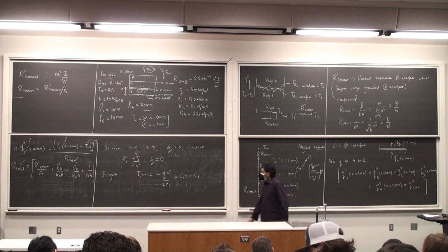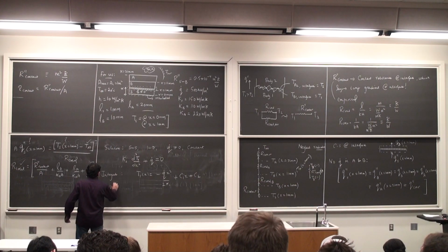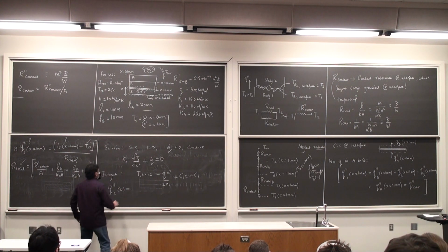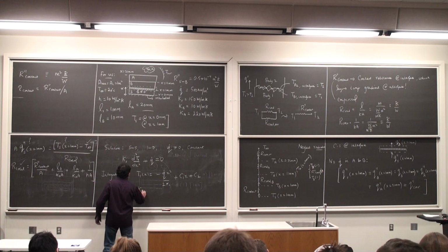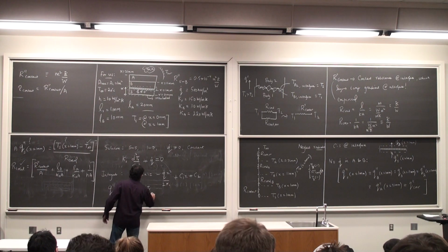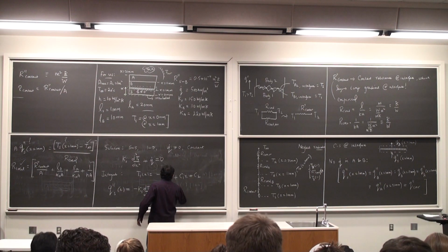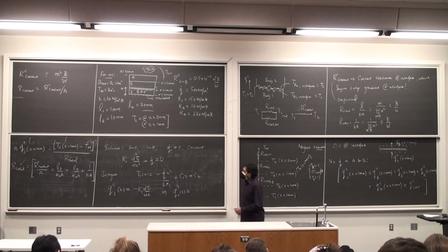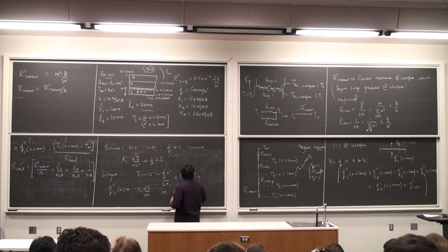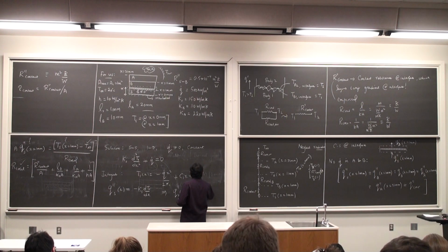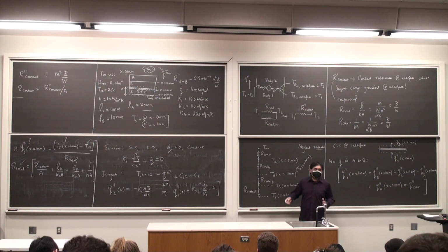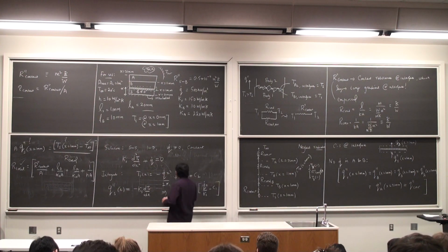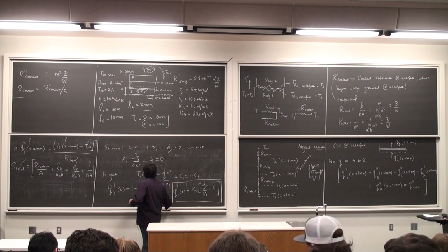I have two equations essentially. I can also calculate the heat flux if you like. So Q double prime of the silicon as a function of x is going to be minus k silicon times dT by dx. And so Q double prime, I will lose the negative sign, right, because I have a minus Q dot. C2 will vanish, and so I'm going to have Q dot x minus Ks C1. Okay, I'm just writing it down because I see that the flux is needed at that particular equation there. So two things.